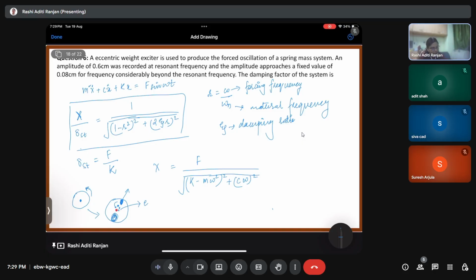For here, it is having some other mass. The difference between these two masses is small m. In that case, the residual force is M omega square E, where E is the eccentricity. And this point is actually changing its place with respect to time, corresponding to the frequency omega. So I can now write F as M omega square E.